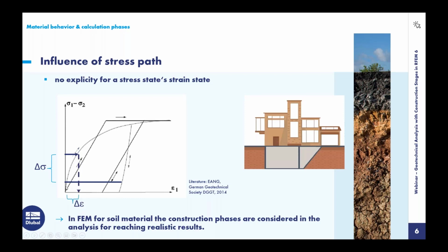If the element had a higher loading before, or at least the same loading or a higher loading, and was unloaded, and like this it reached the current stress state, then it will use the reloading stiffness modulus, and we will have another strain.